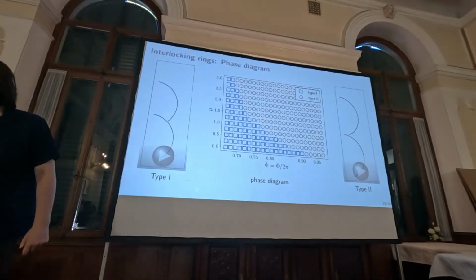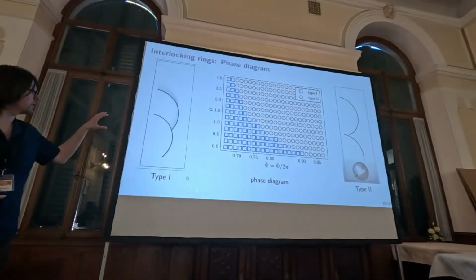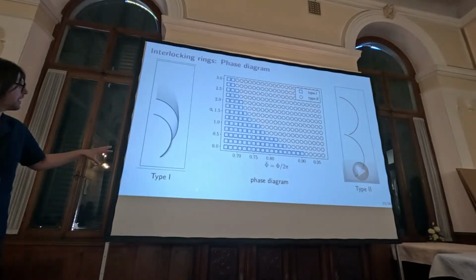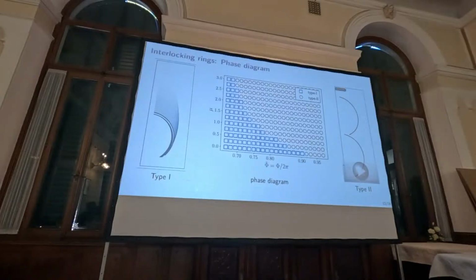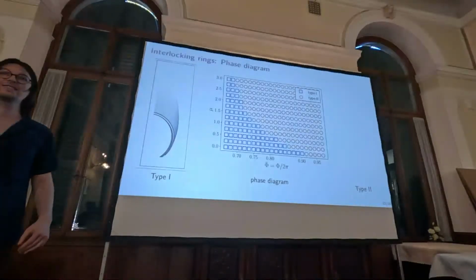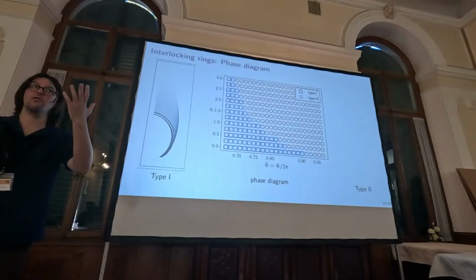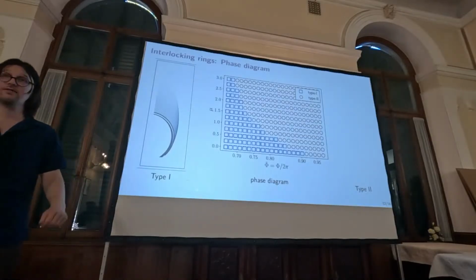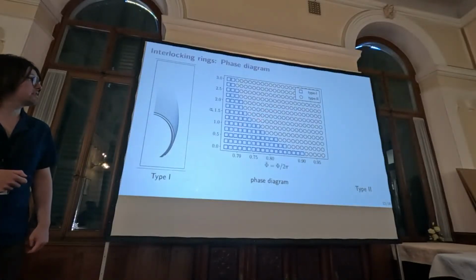And as in that article, we see only two regimes, depending only on the friction coefficient and opening angle. Either what I call type 1, where we slide continuously, or type 2, where it sticks. This video does not want to play, so you'll have to trust me: it sticks, and then it starts to coil, and it snaps suddenly with quite a loud noise, actually.